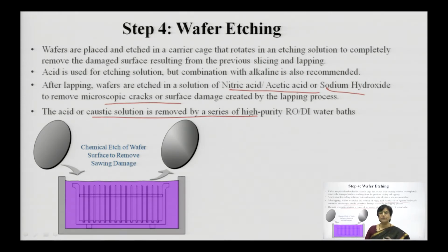Whenever you handle any chemical, post chemical exposure, DI water is essential. So you always use DI water and clean the wafer, or you use RO water.